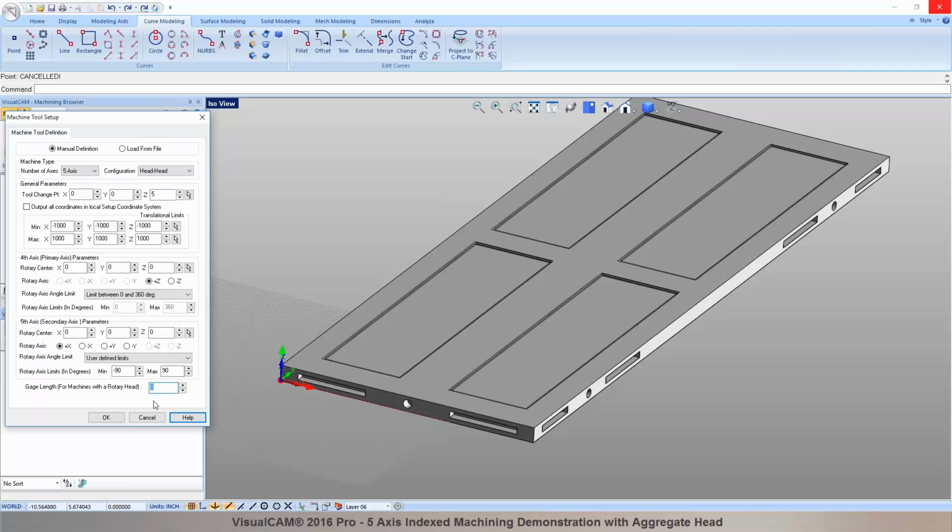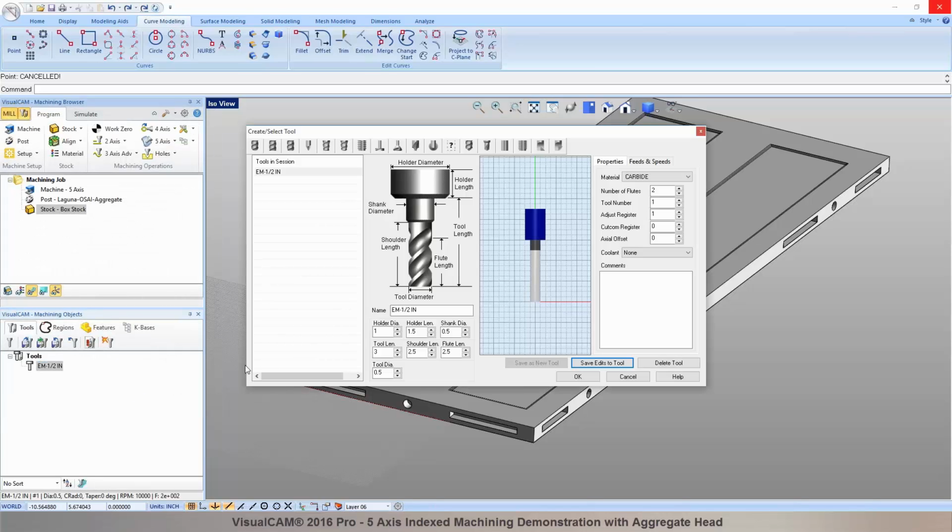So what happens when you change tools out? You want to make sure that you set your tools the same length every time. If you change the tools, we automatically add the tool length to the gauge length parameter that you specify in here to compute the total gauge length. So you don't have to update your code or update it here. You just make sure that the tools you define have the tool lengths in there. That's easy enough.